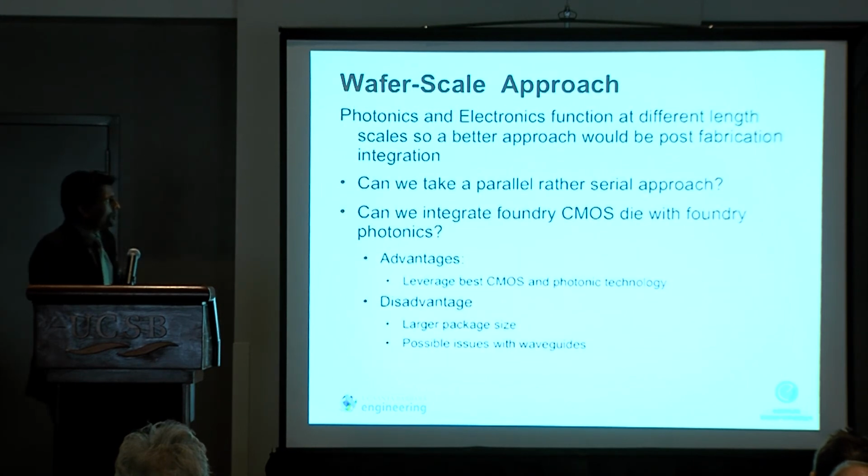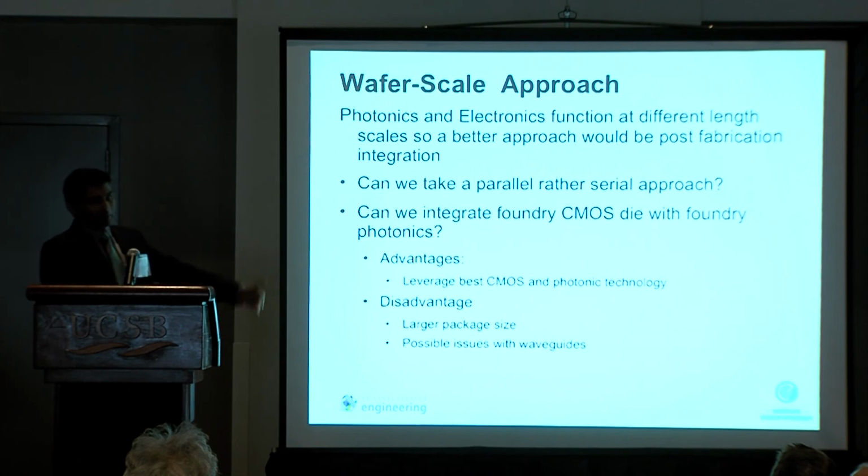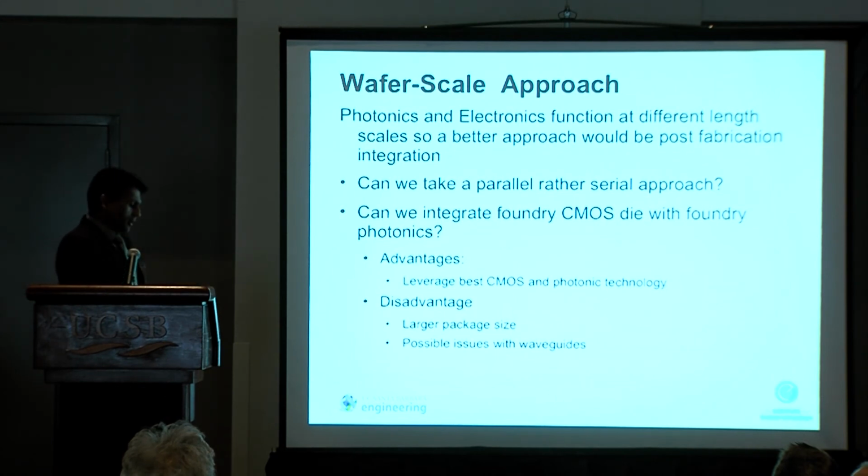So what we try to do is a little bit different. First of all, photonics and electronics have entirely different length scales. Photonics in the order of millimeters, electronics in terms of microns. So you really don't want an intimate integration of the front end of the line. It's better to do it at the back end. And if you do it at the back end, then you can develop two processes in parallel and then join them at the end. So that's the kind of approach that we're taking.